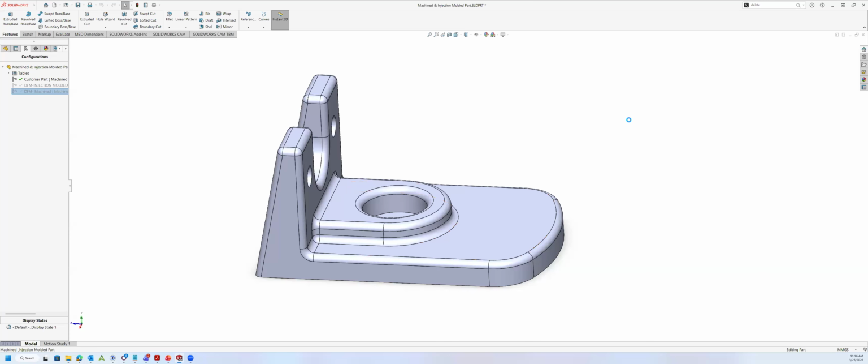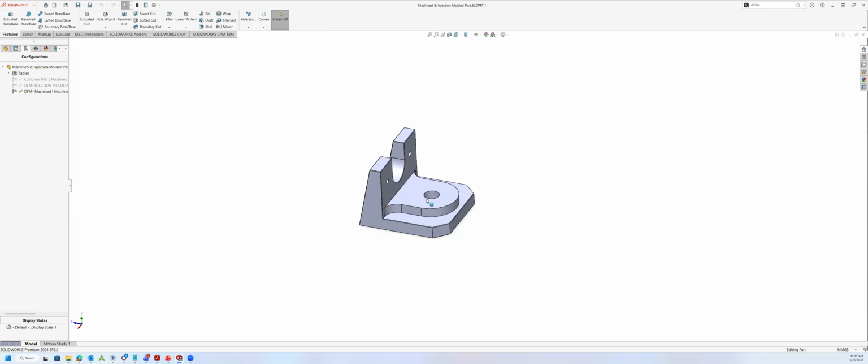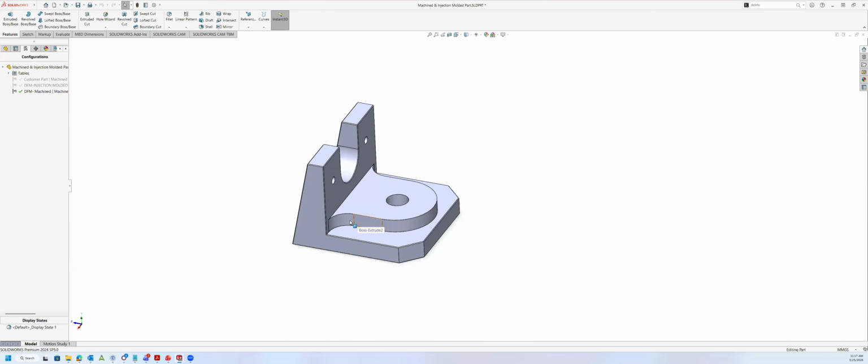So when simplifying and applying DFM principles to this design, we were able to optimize it, as you can see right here. First, we took out all the unnecessary fillets. The one fillet we did include was just right here, to help with your tool path. When it comes to the size of the fillet, you always try to aim for the largest possible fillet you can, but if there's a requirement or something needs to fit in here, you could reduce it.